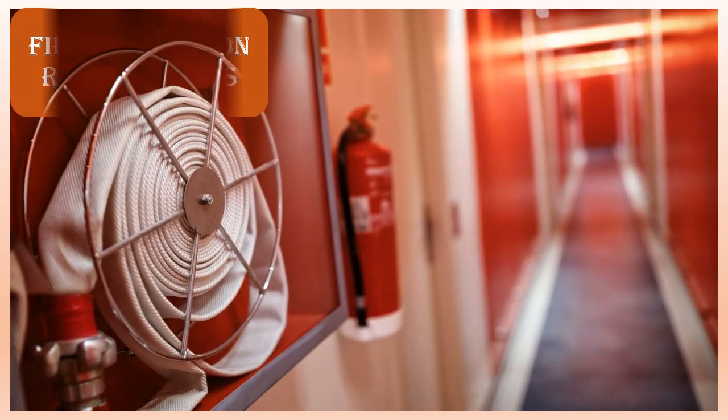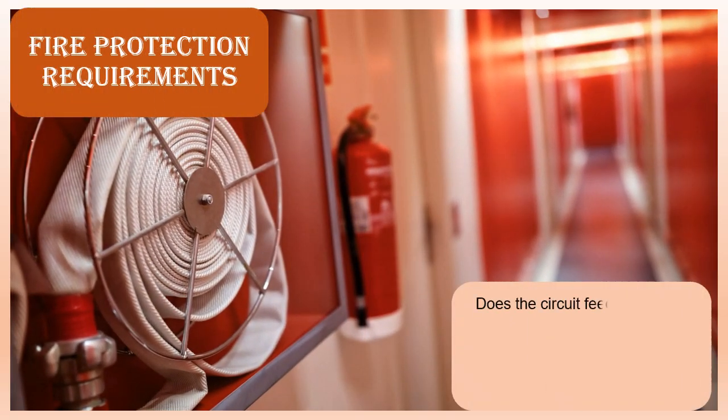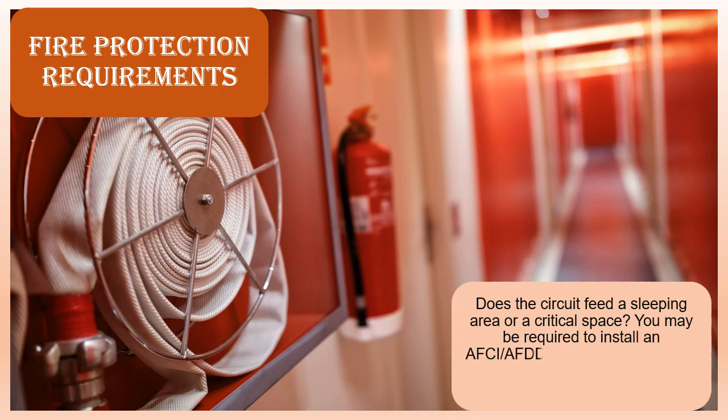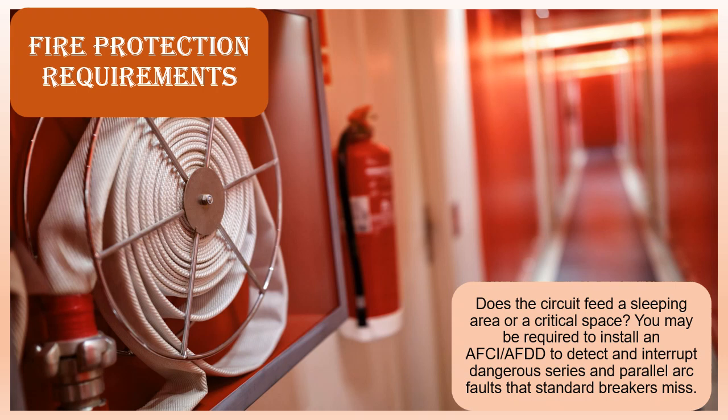Fire protection requirements. Does the circuit feed a sleeping area or a critical space? You may be required to install an AFCI or AFDD to detect and interrupt dangerous series and parallel arc faults that standard breakers miss.